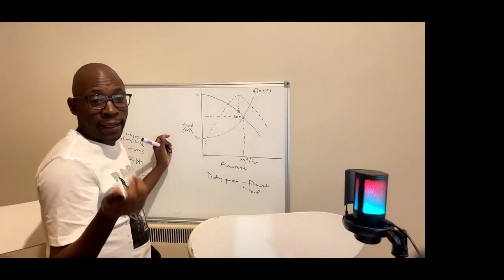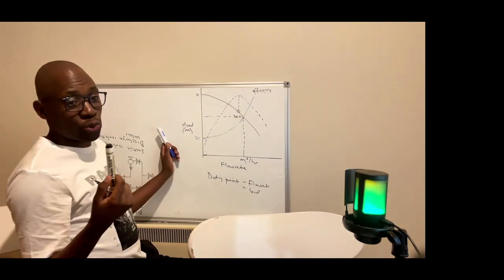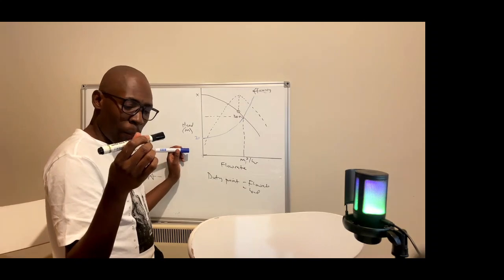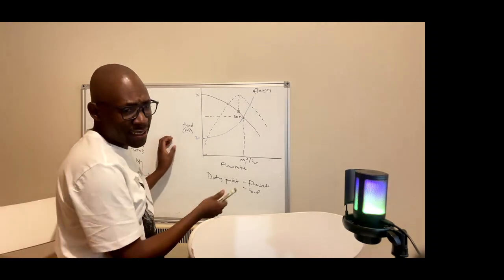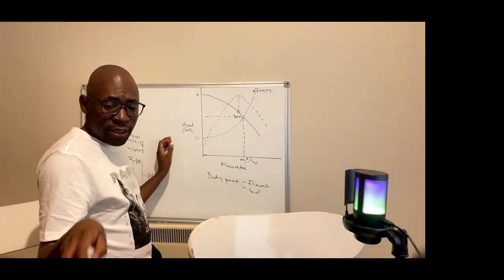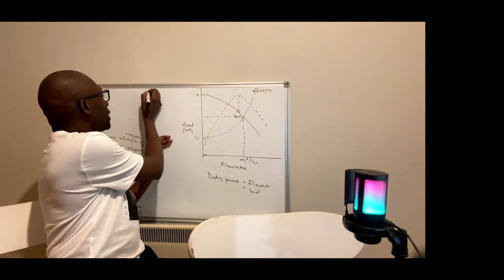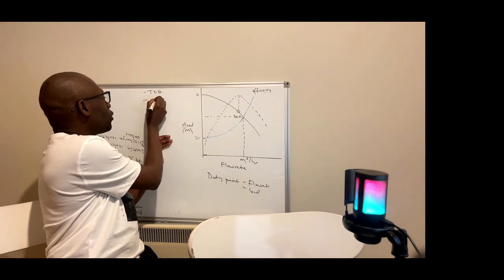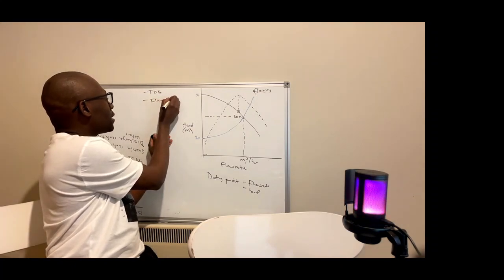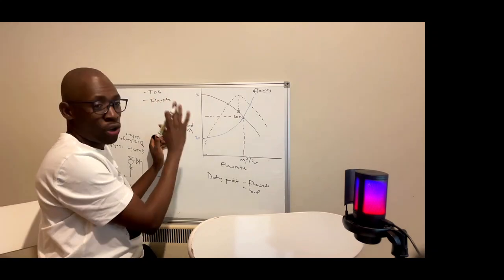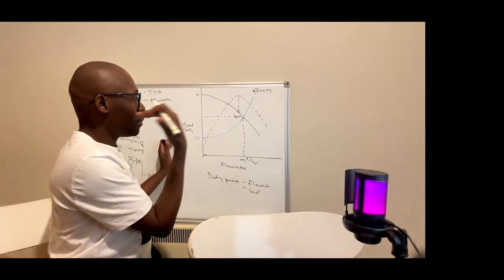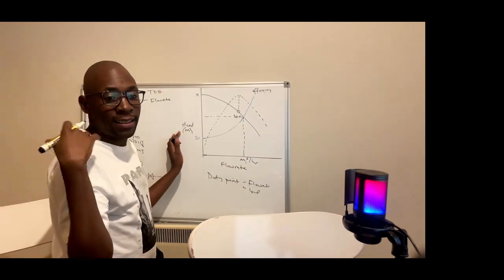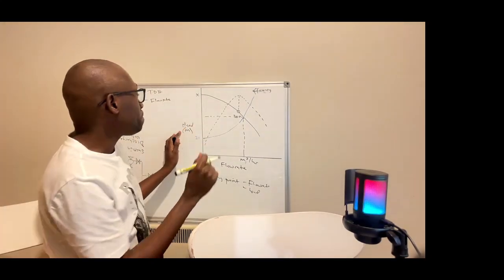Okay, so in this video, I'm going to introduce you to how to read a pump curve. When you are sizing a pump, what you need to have is the total dynamic head and the flow rate required. Then using these two, you can go to a vendor, or you can go to a vendor's website if the data sheet is already uploaded there.